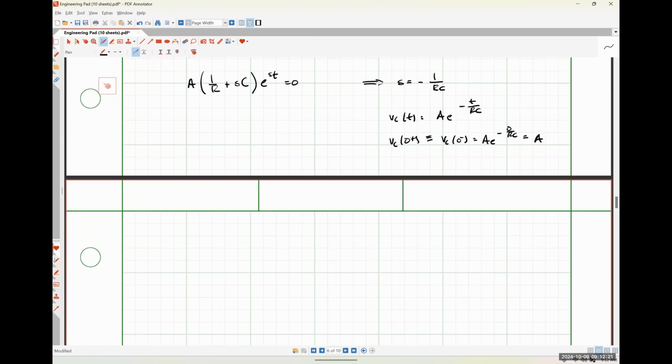And putting those things together, we wind up getting our capacitor voltage VC of t will be VC at 0 minus for t less than or equal to 0 minus, excuse me, VC at 0 plus e to the negative t over RC for t greater than or equal to 0 plus. And we can generic this guy up as well. Since the voltage drop across both of the elements are the same, we can use Ohm's law and all that kind of stuff to find the currents have to be that as well.